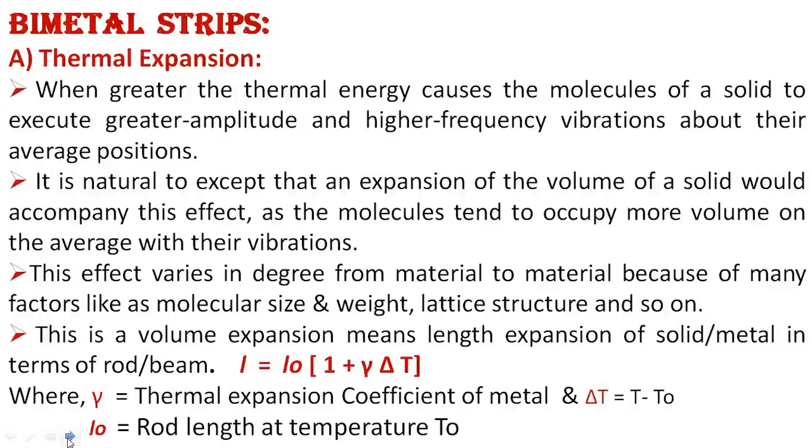This effect varies in degree from material to material because of many factors such as molecular size and weight, lattice structure and so on. This volume expansion means length expansion of a solid or metal in the form of a rod or beam. L is equal to L0 in bracket 1 plus alpha del T, where alpha is the thermal expansion coefficient of the metal, del T is equal to T minus T0, and L0 is the initial length of the rod at temperature T0.